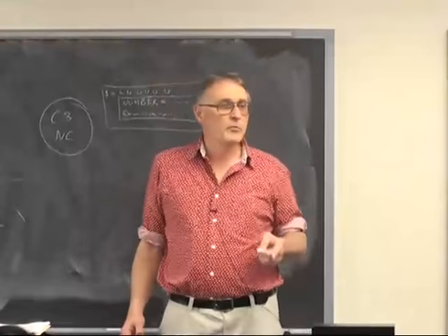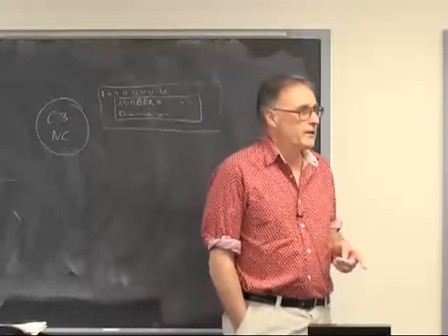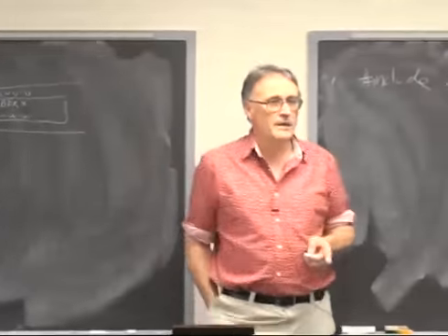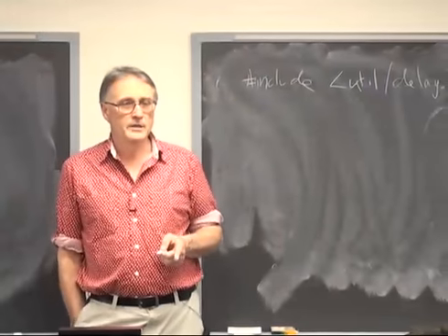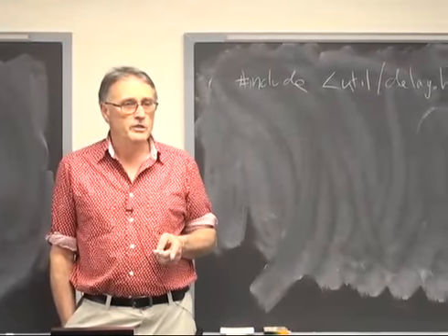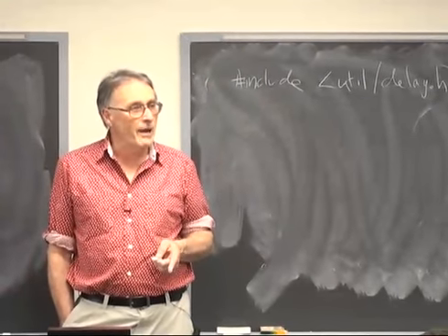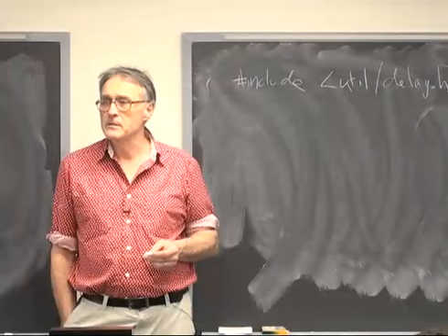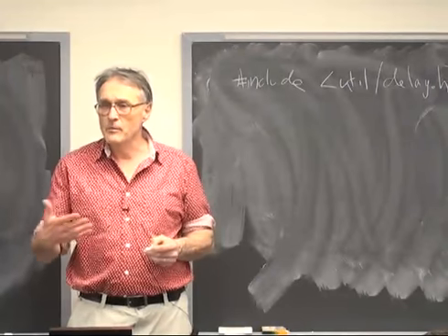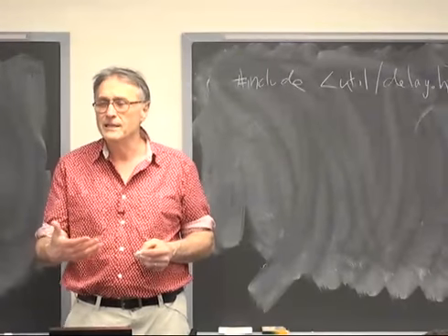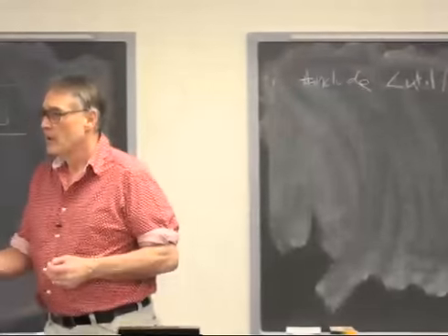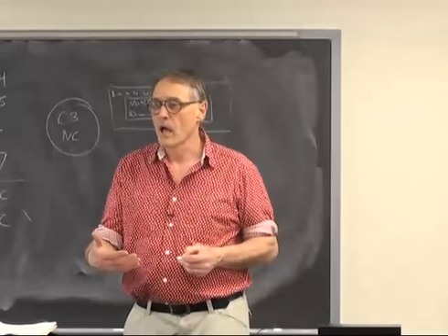And so the symptom, when you forget to set the clock, will be either the LCD doesn't initialize or it shows completely random character segments. Just garbage across the screen. And you should immediately say to yourself, I better check the clock.